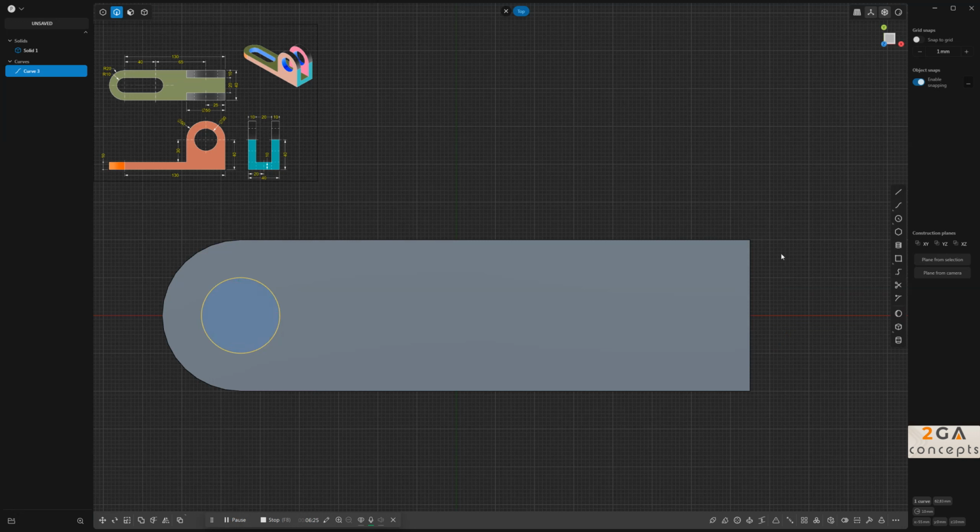For this shape, we're going to use the three-point square or rectangle. So you keep your finger on the left click, and you select straight away the three-point rectangle. There you go. So that's okay. That's 20, and that's 40 here.